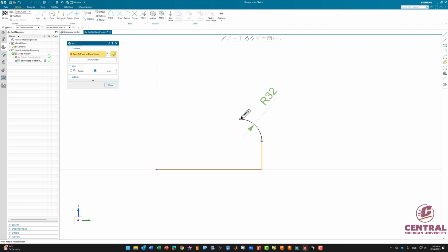So try to get close to where it started. So that's where I want to have a tangent. All right, so I have a click, then I'm gonna go down more. Then if you go down enough, when it's lined up with the existing one, you can see it will snap also. So just be patient a little bit, give a little time, the NX will give you the best suggestions you can use for your sketch. So at this point, I like the way it picked it up for me.